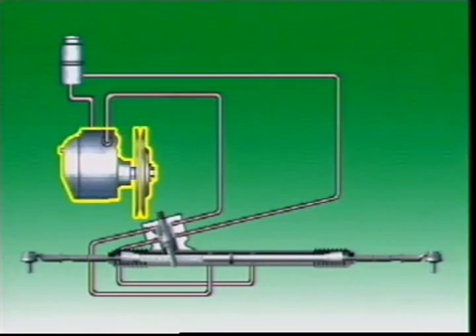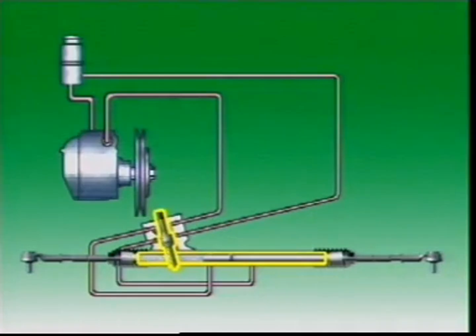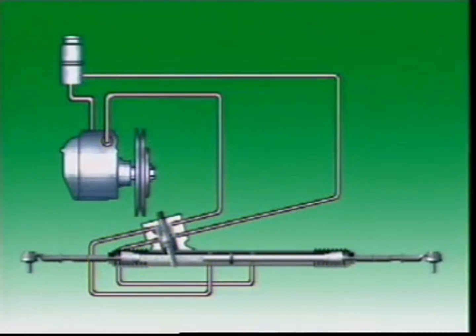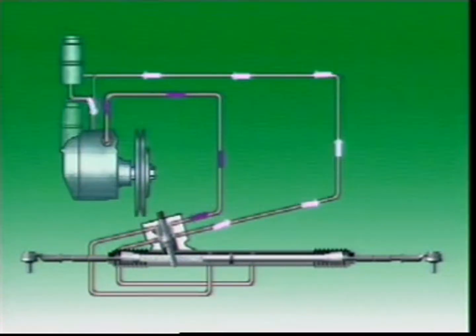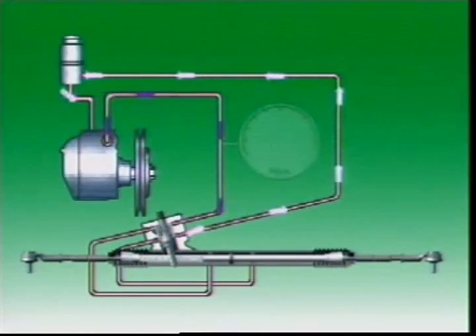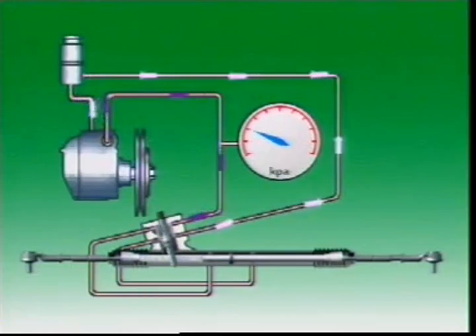An engine-driven hydraulic pump delivers hydraulic fluid to the power unit at the steering box or rack and pinion through connecting hoses and pipes. The fluid reservoir can be mounted on the pump, or it can be separate. With the engine running, fluid flows continuously from the power steering pump to the steering gear and back to the pump. With the steering wheel in the neutral position, little pressure is needed to maintain fluid flow, and little engine power is needed to operate the system.